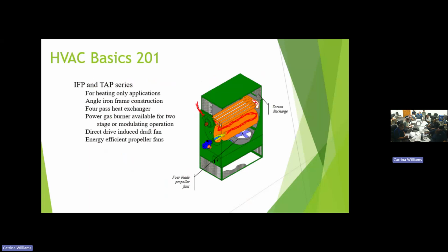Now, that's a small number, right? This unit here, the largest model is 150,000 CFM. You would have 3 fans versus the 2 shown with 150,000 CFM. Put that in perspective: 150,000 CFM at 0.075 is 11,250 pounds of air per minute we're moving. Now you know where the horsepower comes into play. Over 11,000 pounds of air every minute is going through that unit.